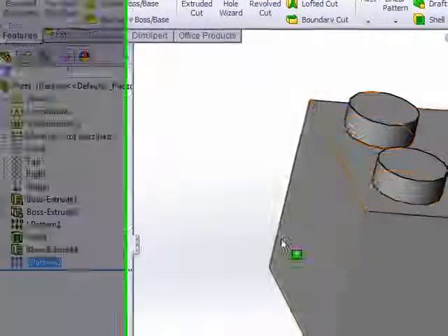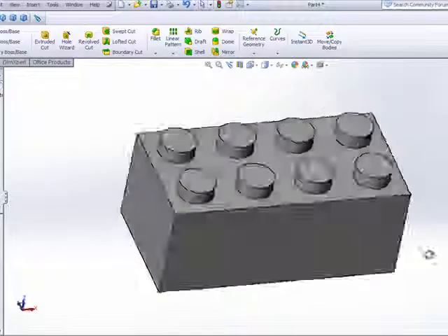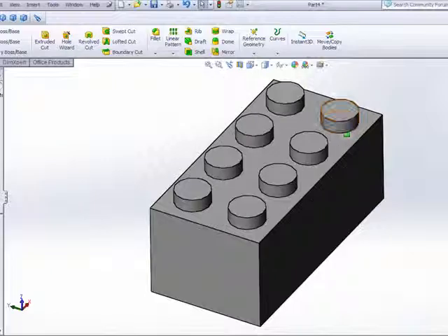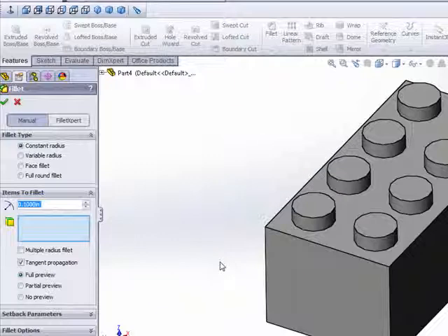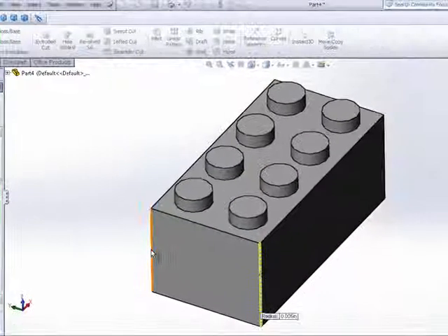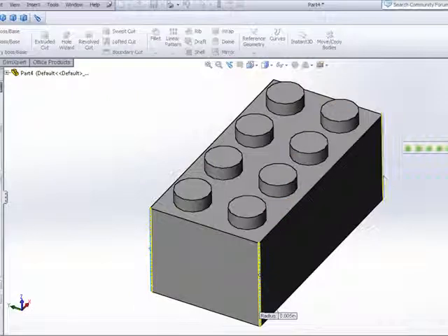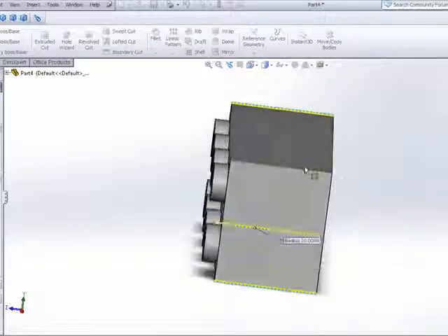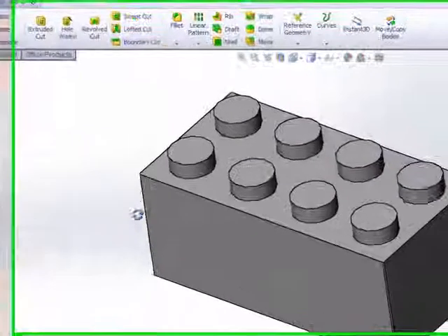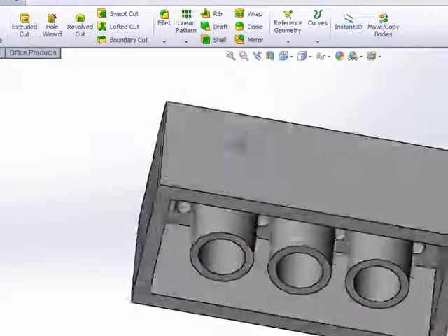Now, one thing I did notice when I was machining is that in my CAM package I can corner around, but I'm getting a very sharp corner, and really the Legos have a very small fillet on them. It looks like about 5 thousandths. I don't really have any way to measure that exactly, but I'm going to put it on there because when I take it to my CNC, there we go. All right, so that's the basic Lego brick, and it looks complete.